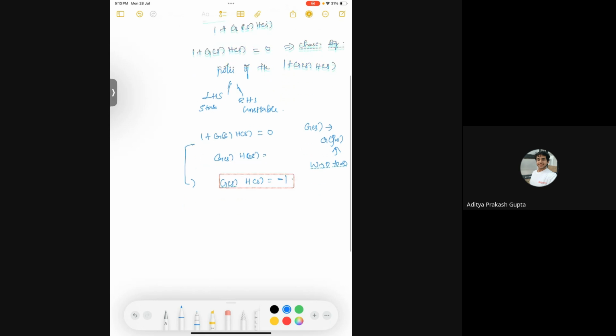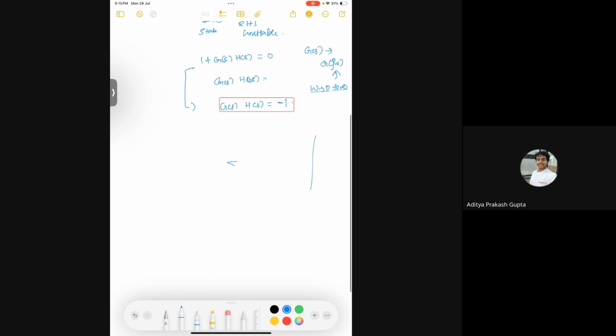Instead of seeing whether the Nyquist plot has contoured clockwise or anti-clockwise around the origin, we are going to see with respect to -1. That's why always in the Nyquist plot, we will consider -1 as the origin, since we are dealing with only the open loop system, not the closed loop system.